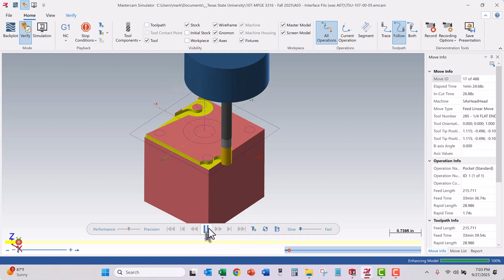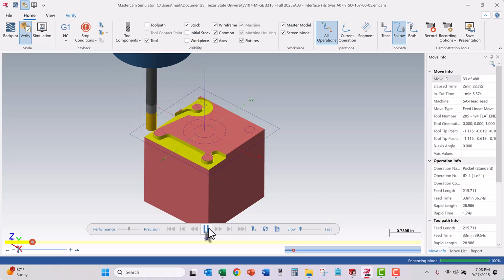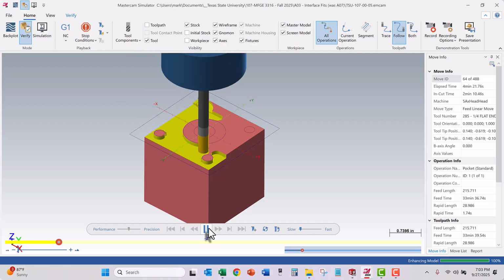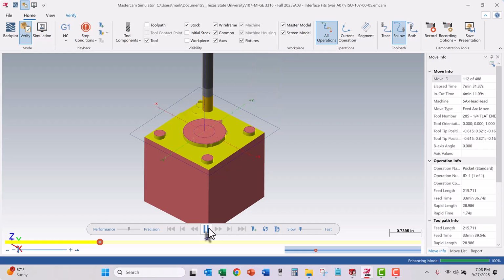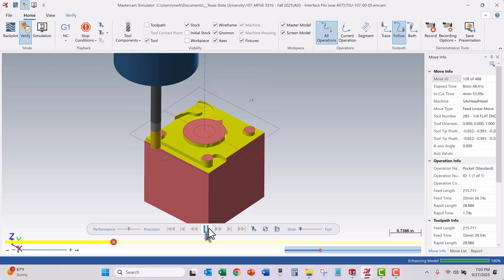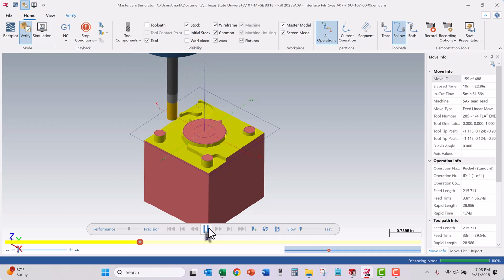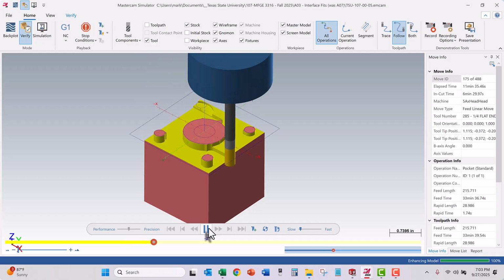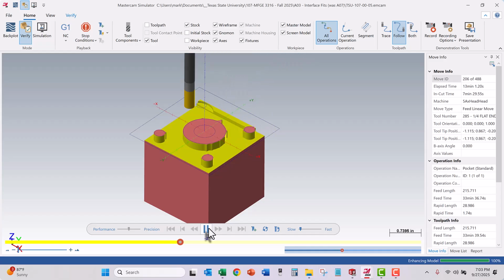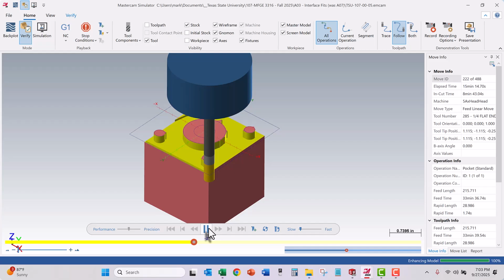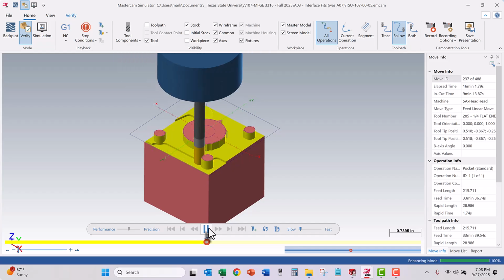So it's going in. This is the first roughing pass. Looks like it's leaving my post like I want it. And you can see that tool goes beyond the edge of the part so that it gets a full cut. So that's why I had to offset those lines a quarter inch from the edge of the part. So that looks like this is pass number 2. And I asked it to go down no maximum step down 1/8 of an inch. So it's wrapping around there and did that one. Now it's going back and doing a third roughing cut, looks like.